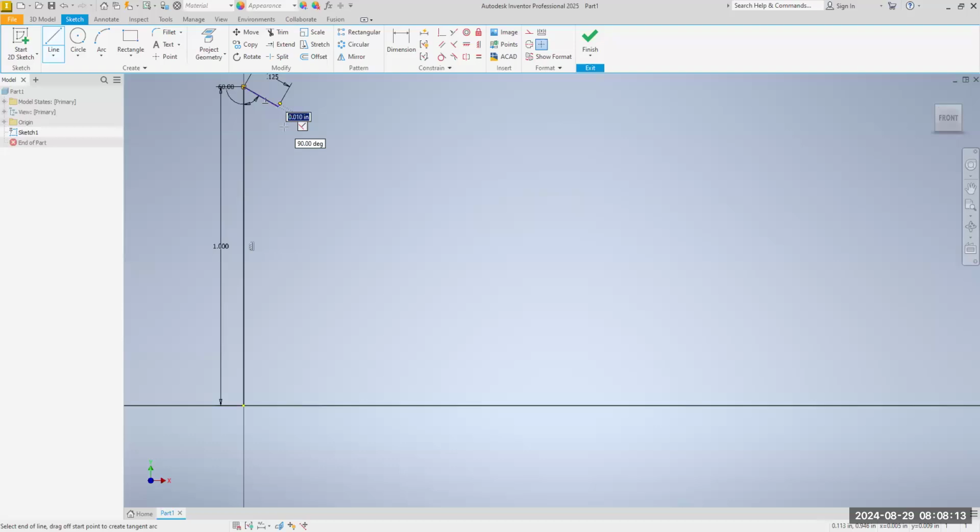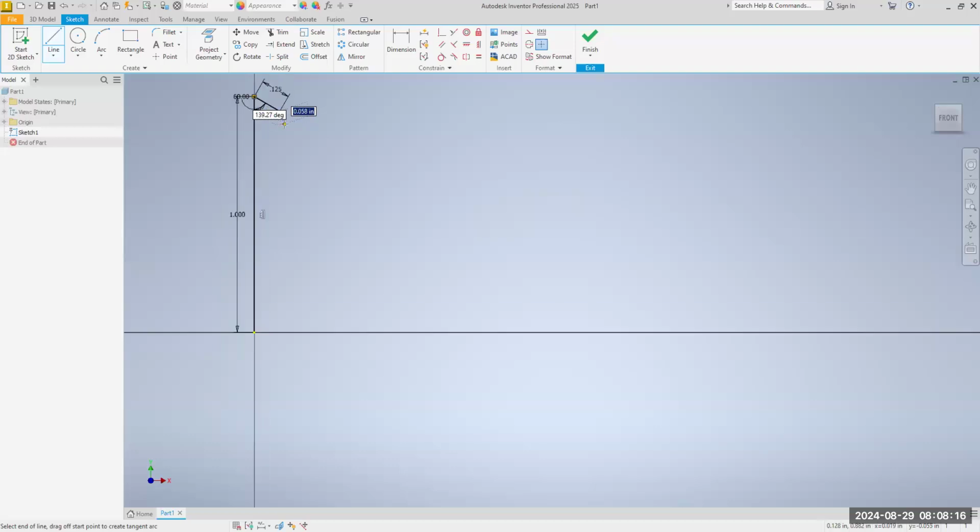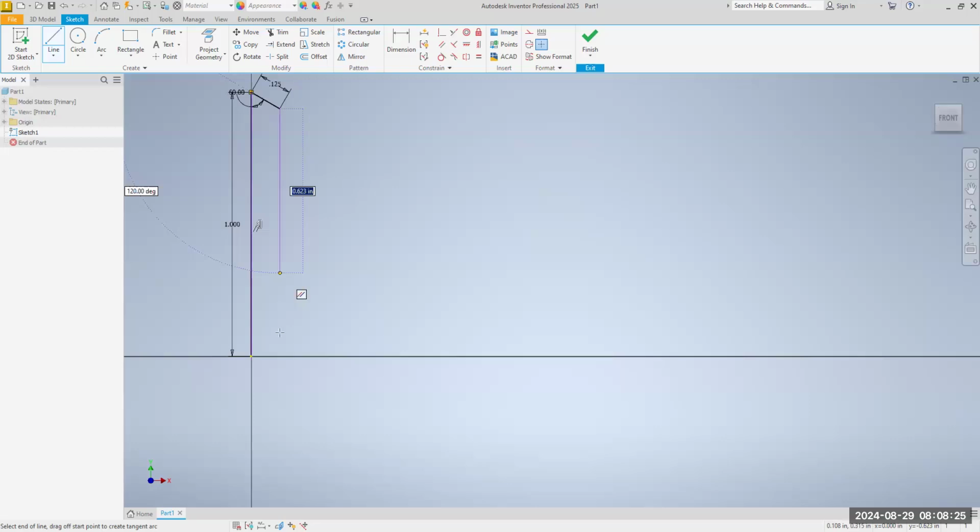All right. Now I can zoom out. If you want to zoom out while you're drawing, you just rotate the scroll wheel to zoom in and out. Okay. Now I'm going to come down this way and make this vertical dimension here. Look, the line is following my cursor. So I'm going to come straight down and make sure that this line is going to be perfectly vertical. So I'm going to type in 0.875 and hit my tab key. Again, I don't expect you to memorize any of this. I just want you to watch.